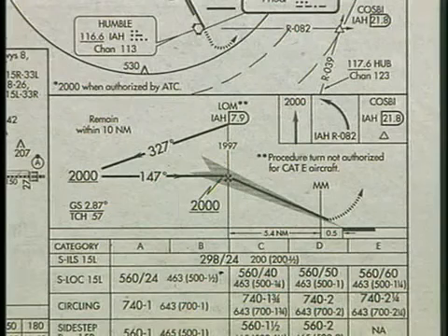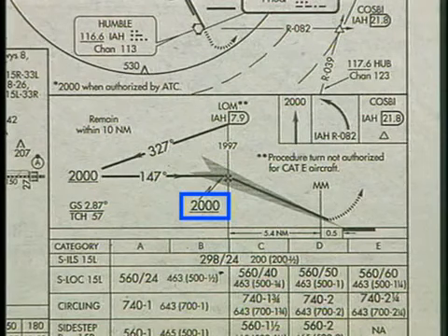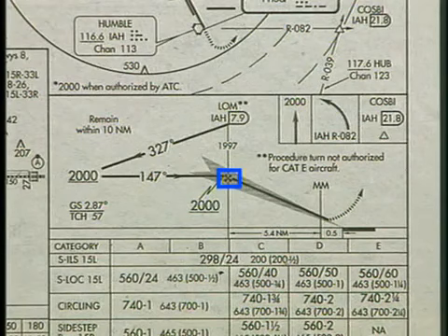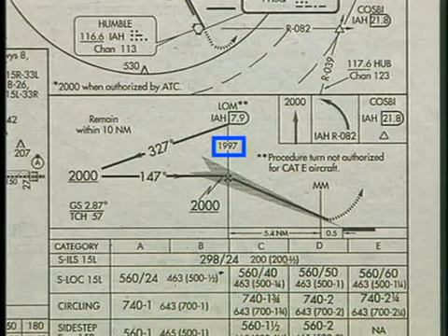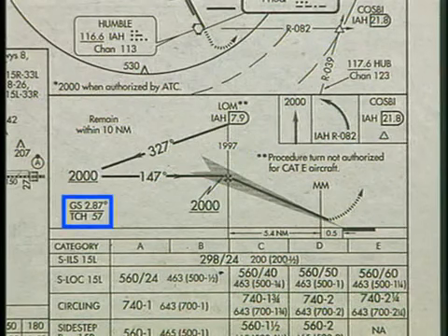The profile view depicts the glide slope intercept altitude along with the non-precision final approach fix. Also shown is the altitude of the glide slope at the final approach fix. The glide slope angle or descent angle may be shown with the threshold crossing height or TCH.